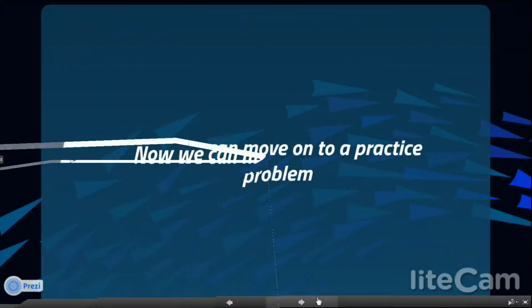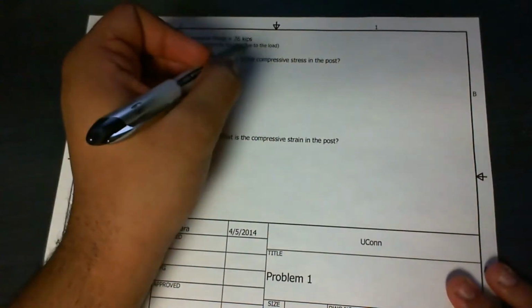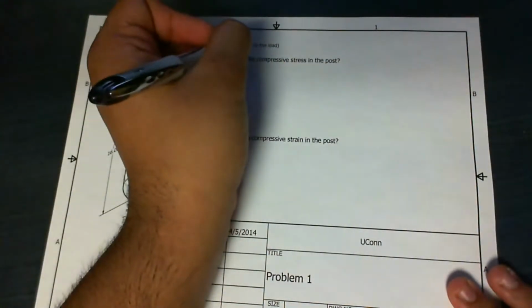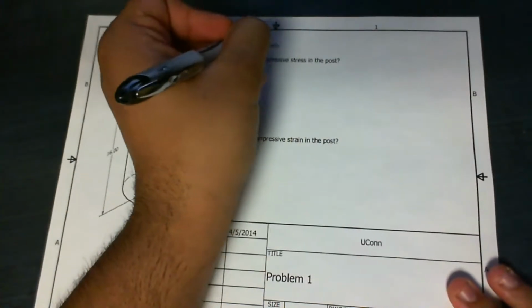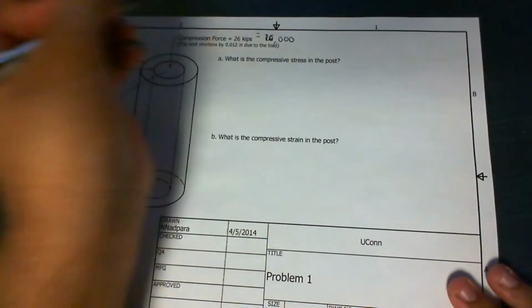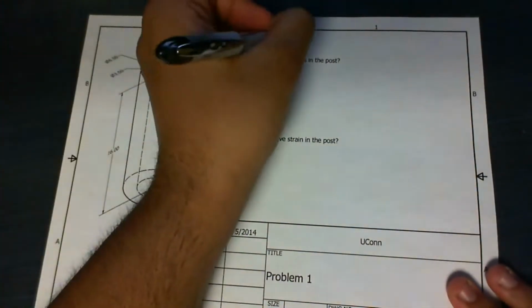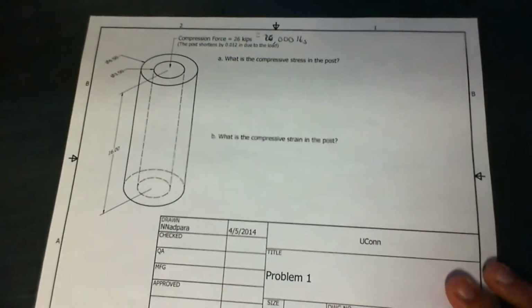Now that we've gone over the basic concepts of solid mechanics, we can move on to a practice problem. The practice problem we're going to do involves a hollow circular aluminum post, which supports a compression force of 26 kips. Now 26 kips is a unit of force. It's also equal to 26,000 pounds, because 1 kip is equal to 1,000 pounds. So we can substitute 26 kips for 26,000 pounds.